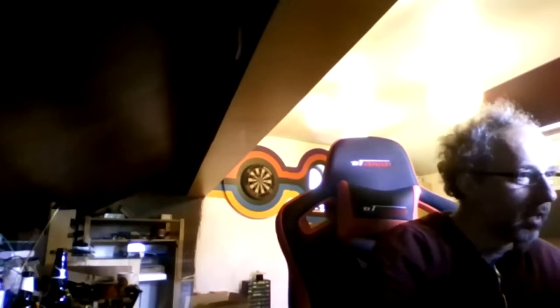The problem I had with part of it was there's like 2 ground planes separated by a load of wires, so I just ran out of routing space. And it goes from one side of the board to the other and back again. So the return path was quite tortuous getting around this area. Would it have been sort of, I don't know, a kosher way of doing it, of just putting a whole bunch of wires in instead of 1 or 2 to reduce the impedance when you're transitioning from one side of the board to the other? Or is it a real bodge?